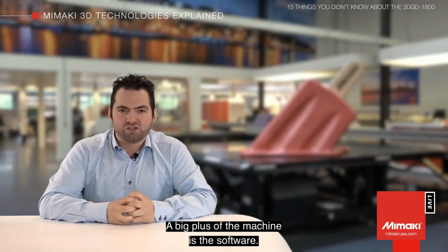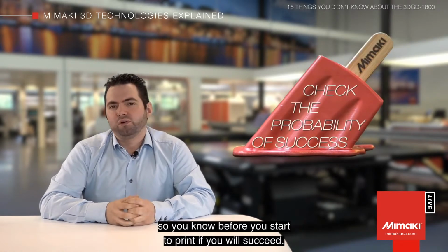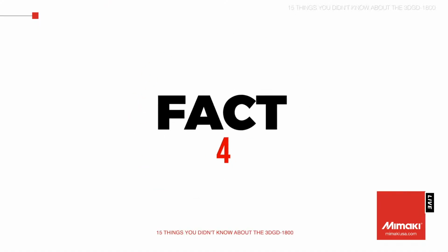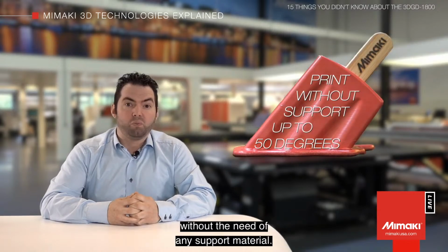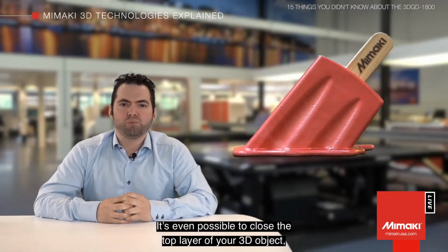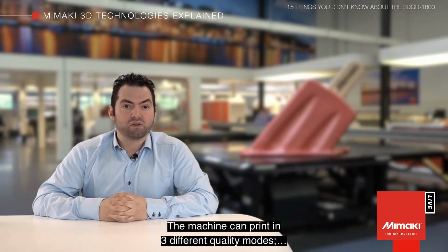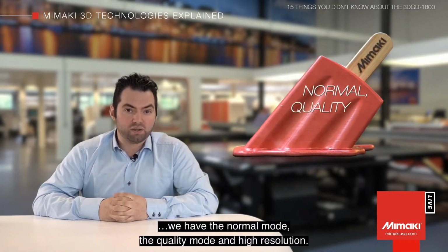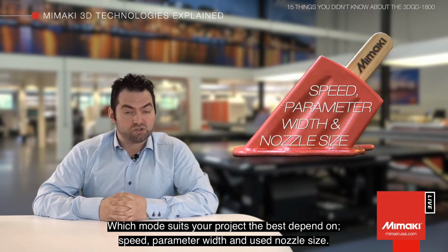A big plus of the machine is the software. We have special tools inside our software that check the model, so you know before you start to print if you will succeed. In general, we can say that this machine can print overhangs up to 50 degrees without the need of any support material. It's even possible to close the top layer of your 3D object without the need of any support material or infill. The machine can print in 3 different quality modes. We have the normal mode, the quality mode and the high resolution. Which mode suits your project the best depends on speed, parameter width and used nozzle size.